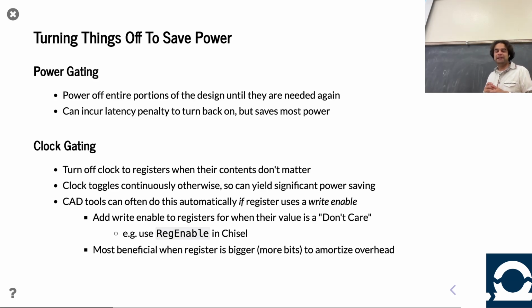And so they can go in and do this. And the only reason I mention it in today's lecture is there's a little bit of help you need to give them as a designer. So you might think when you're writing Chisel, if you use Reg versus RegEnable, so Reg, of course, is the register. RegEnable allows you to have an explicit enable signal in your register, right?